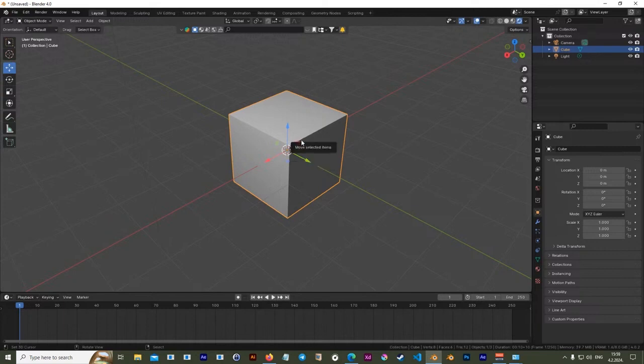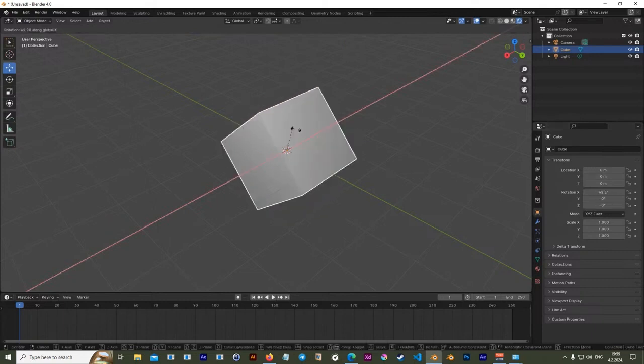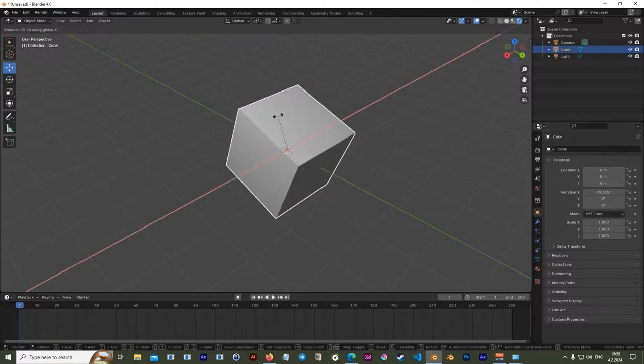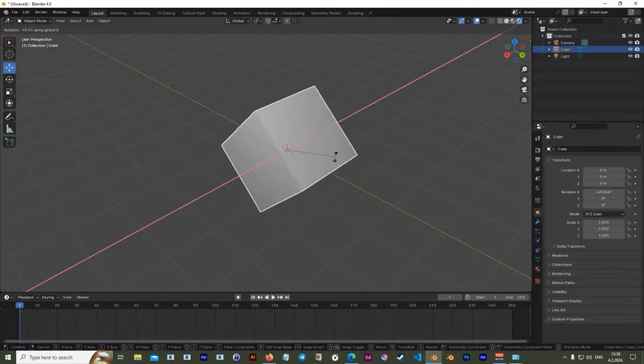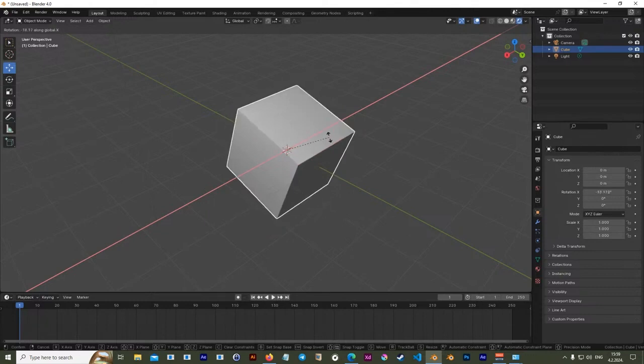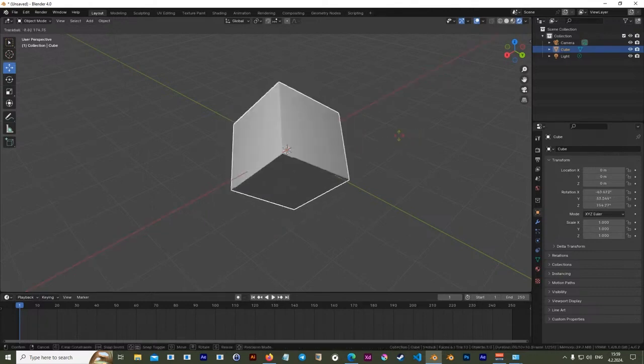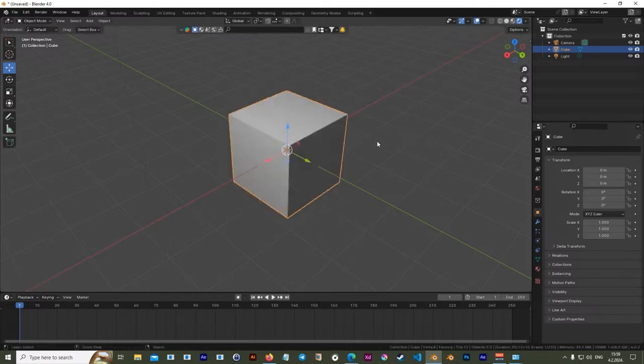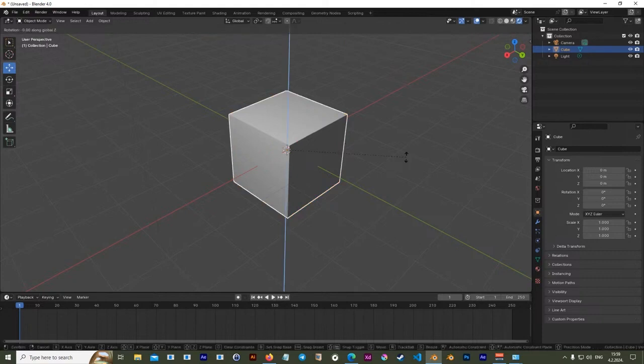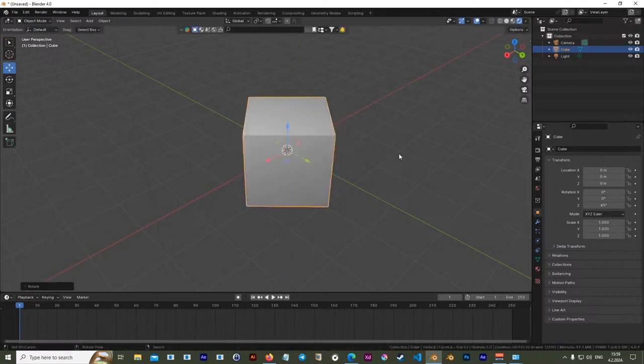Let's try to rotate. Press R on keyboard, press X, you rotate it. With your mouse, of course, but you use shortcuts to access transformations. Rotate it by epsilon. Okay, undo. You can also press R, epsilon, Y, and add input on your numerical keyboard, for example, like 45.